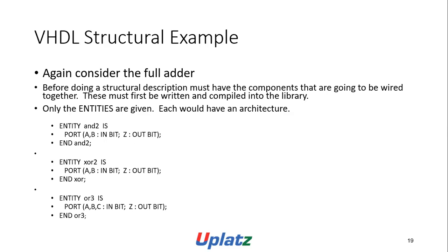VHDL structural example. Again, consider the full adder. Before doing a structural description, we must have the components that are going to be wired together. They must first be written and compiled into the library. Only the entities are given. Each would have an architecture.